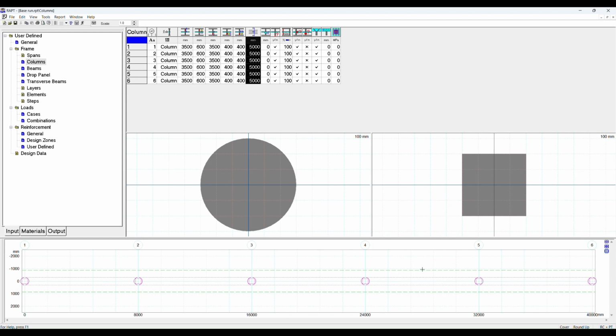So if we were to look at this slab here in plan, we can see that the beam can transmit a bending moment into the column at the face of the column. But there is also a portion of bending moment that's transferred via a torsion strip on either side into that column. And the equivalent column method is all about calculating how much that torsion strip can transmit. There are many textbooks with more information if you want to know more.